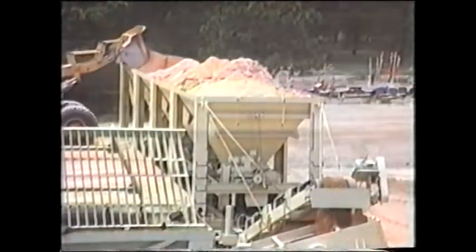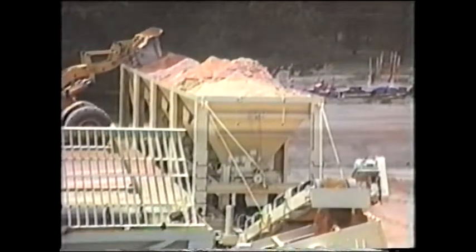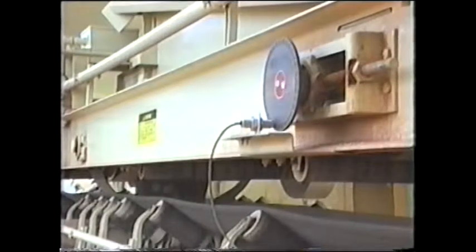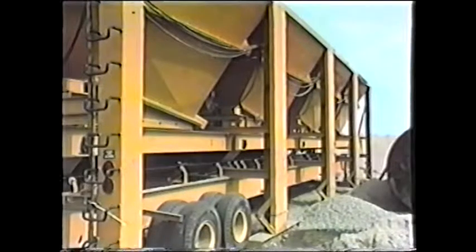Impulse automatically controls cold feed material flow in one of two ways: either volumetrically, based on the speed of the feeders versus a final belt scale, or weighing each material separately by placing a belt scale between each aggregate bin. Materials are then controlled according to the mix formula entered and the individual moisture contents of each aggregate.